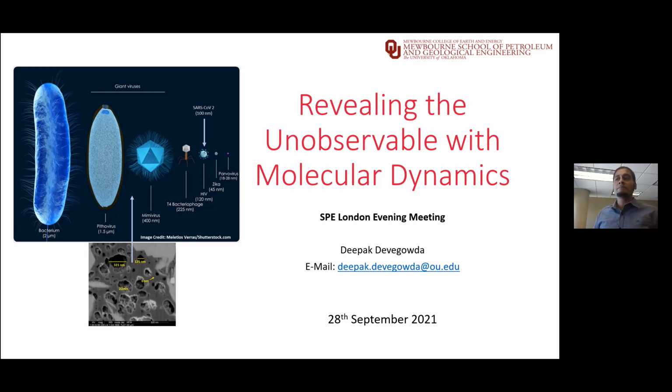But the same fluid confined in a very small space would have a suppressed bubble point, maybe closer to 2,000 or 3,000 psi. We're seeing that with dew point fluids as well. And as to your point about solubility, absolutely. Methane solubility has been shown to go up by close to an order of magnitude, depending on the pressure and temperature conditions.